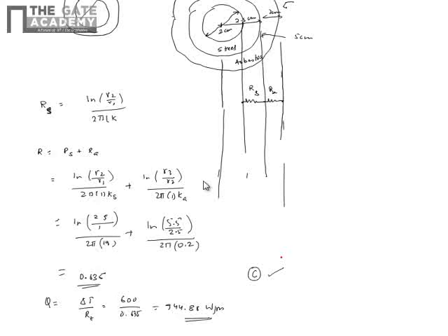Only thing is you need to remember the resistance offered in steady state radial heat transfer, the thermal conductance. These expressions are derived for cylinder, and likewise for radial heat transfer through a sphere, so you need to remember them to solve these problems quickly.